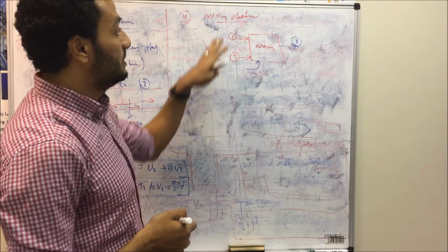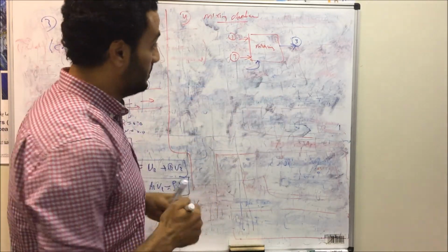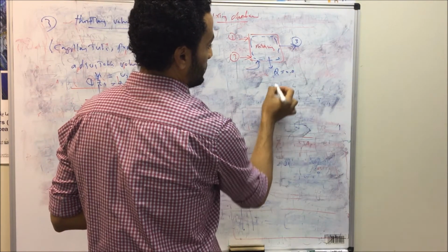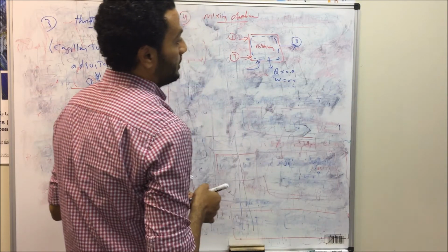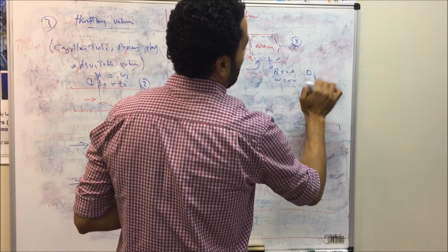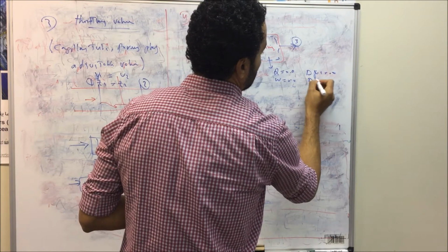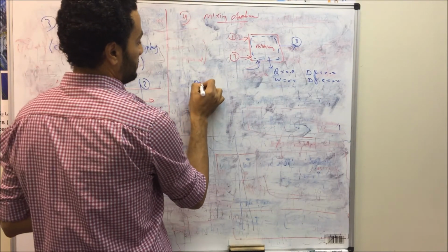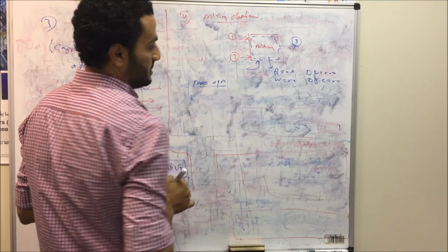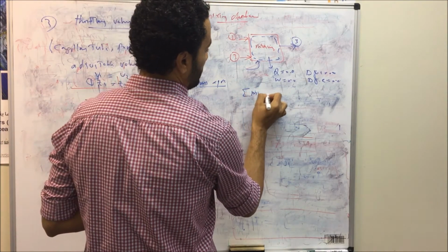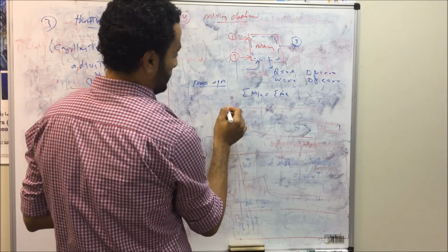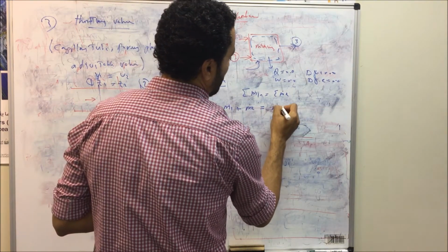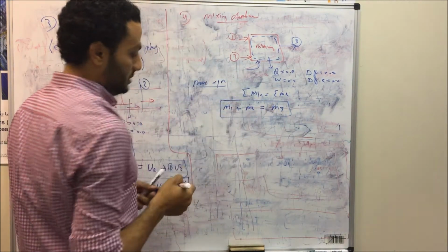It's okay. Whatever the number of inlets, whatever the number of outlets, in this case we have heat exchange inside, but externally we don't have heat transfer, so Q is 0. In this case the work is also 0. The change in kinetic energy is neglected, and the change in potential energy is also neglected. So if you look at the mass equation, the system is a steady flow, so summation of m dot inlet equals summation of m dot exit, or we can say m dot 1 in this case plus m dot 2 equals m dot 3. This is the mass equation in this case.